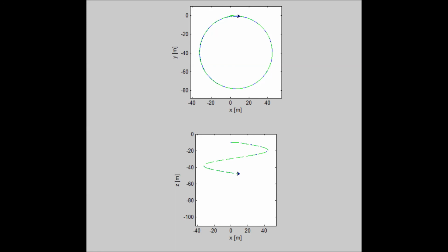This simulation is sped up. In reality, the TBM would move much slower, and I could have used a step input to demonstrate the time to retract the thrust cylinders. The model was able to verify the desired motion could be generated based on the kinematics of the TBM, and that the position could be tracked very accurately, assuming that the position information could be gathered by the surveying system that was mentioned earlier. The orientation of the TBM was also found to be tracked rather accurately with the use of the extended Kalman filter.